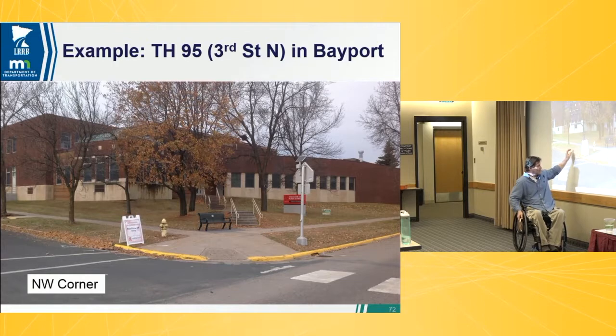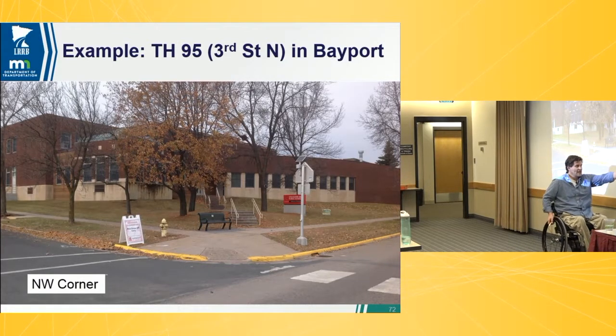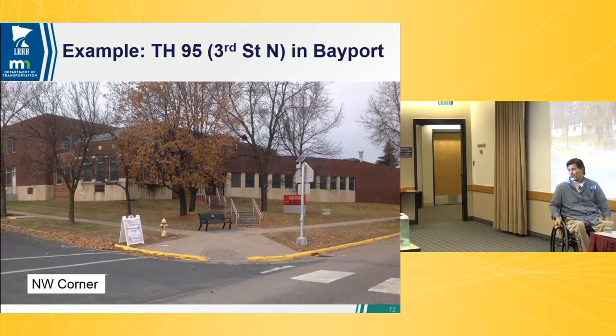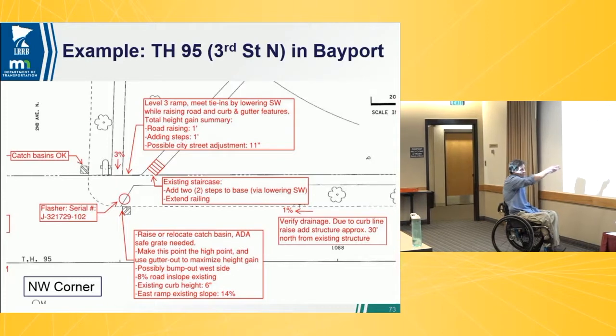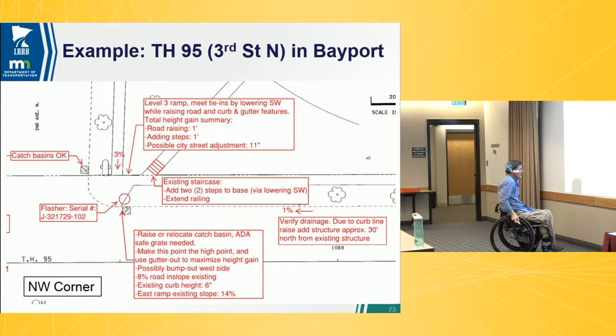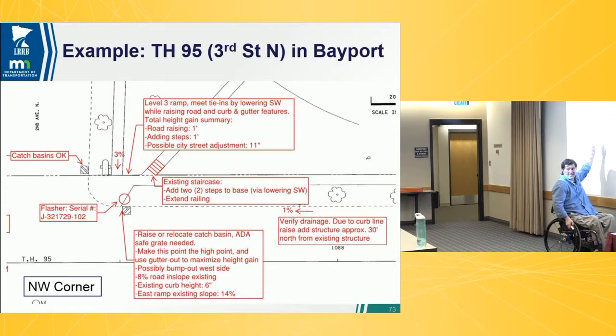So again, the drainage is coming around the corner here, and this is the low point. So I'm locked here, because actually the drainage is coming in from the other direction too. So I got to find something to do with that catch basin. And again, there's that 1% drainage coming in. So I'm going to try to move this catch basin out of here, because I want to raise this flow line.